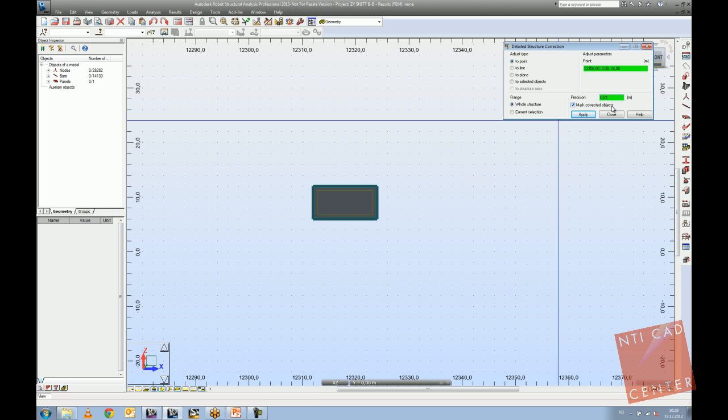Basically what it will do is check the whole structure and see if any of the elements are offset from the axis. So for example, having a little bit of offset of a few millimeters, it will automatically snap it to the axis. So align it where it needs to be, close the small gaps, and it will automatically highlight which elements have been modified. So basically you will have control, you will be able to modify your elements.